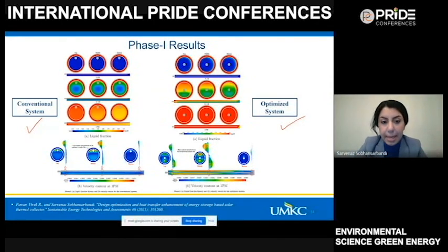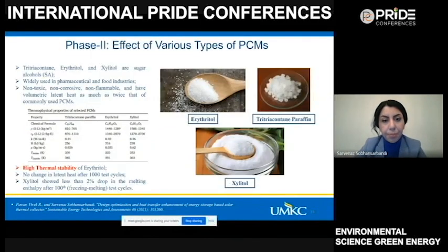It shows how the melting process of the PCM happens, and as you can see on the right, we have a much better liquid fraction, and much better phase change process happening. And as you can see, at 1 p.m. we have our system fully melted. I mean, the PCM is fully melted within the collector, which helps me store energy faster, as well as delay the release of the heat on the other side when the system starts cooling down.